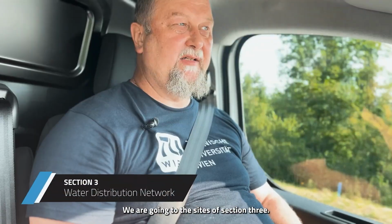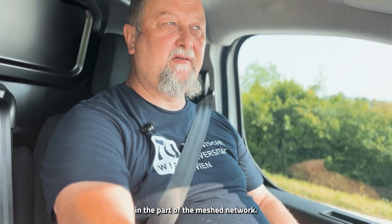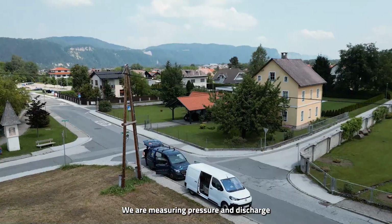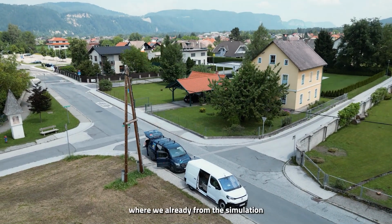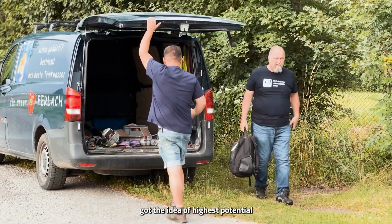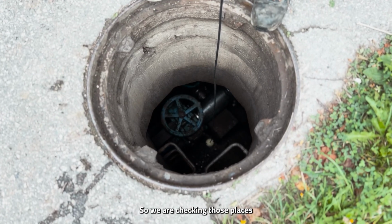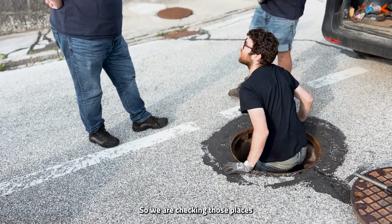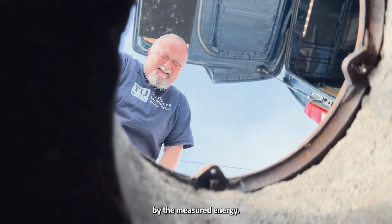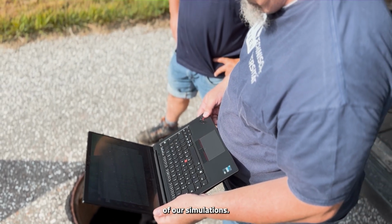We are going to decide section 3, so we are installing sensors in the part of the meshed network. We are measuring pressure and discharge on different places where we already from the simulation got the idea of highest potential for energy harvesting, and that's what we are doing today. So we are checking those places by measurement to compare later on the calculated energy by the measured energy. So that's kind of validation of our simulations.